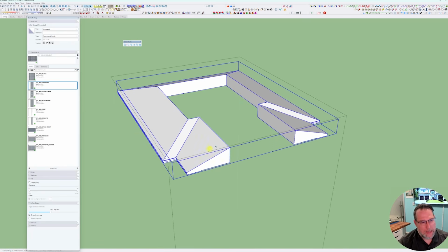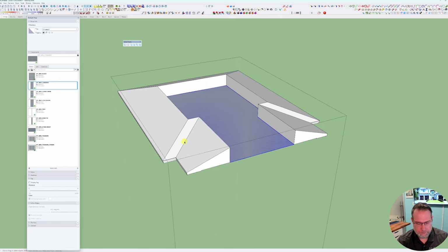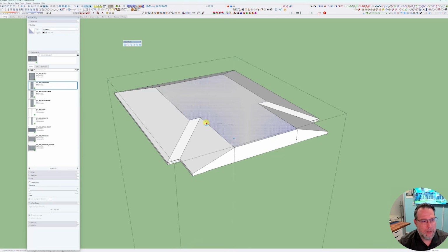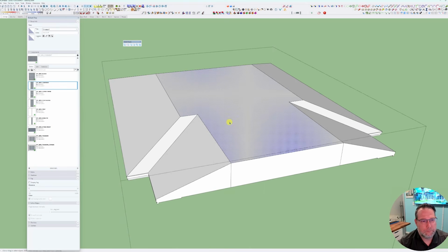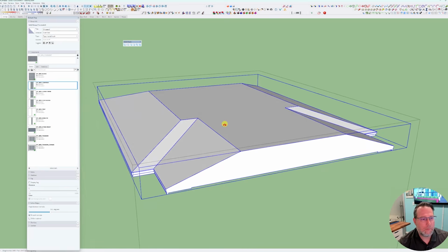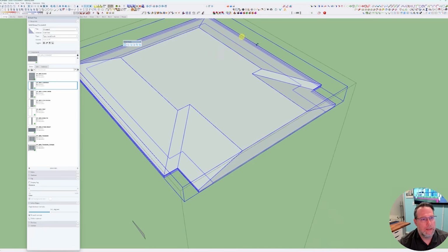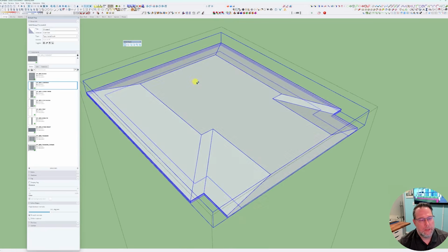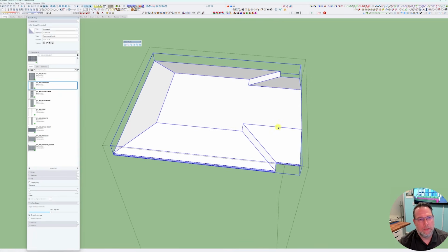So now this is back into being its own solid group, and I'm going to paste in place the outline that we created. I'm going to pull that up, and I'm going to match it to the height of my current roof. Triple click this, Control G to turn that into a group, and now I can Alt C and outer shell this piece to this piece, and we've now just filled in that donut hole, if you will. So we have the beginnings of a really clean roof.